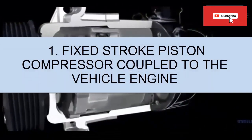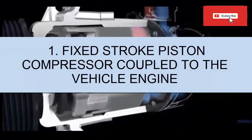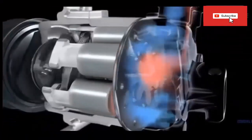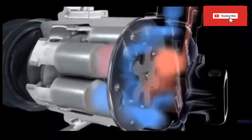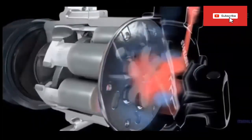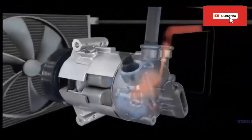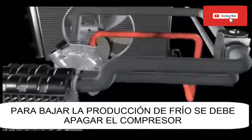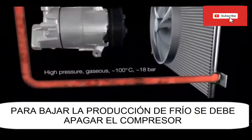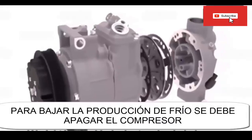1. Automotive fixed stroke piston compressor with clutch coupled to the engine of the vehicle. A. It is a multi-piston compressor driven by a fixed stroke plate used mostly in medium to high power vehicle engines. B. The compressor does not have any system to adapt to the required thermal load in the car. C. The system turns the compressor off and on, disconnecting and connecting the clutch to suit the load of the car.